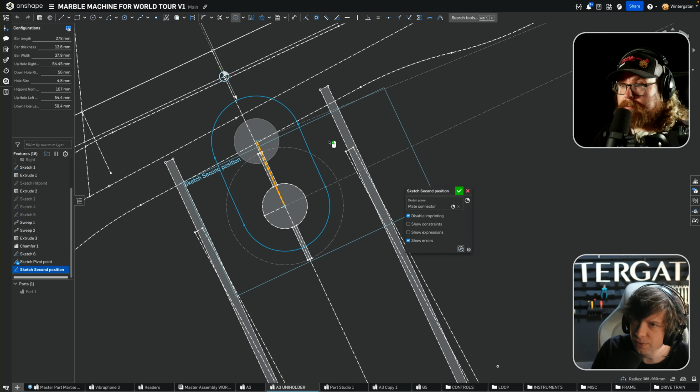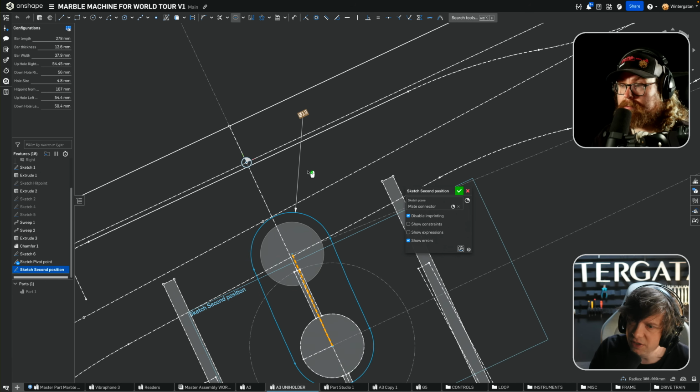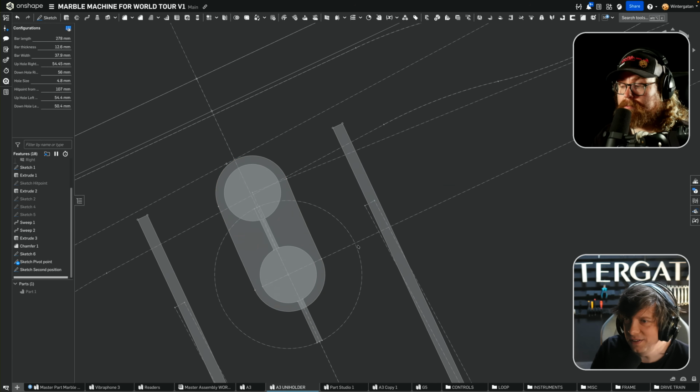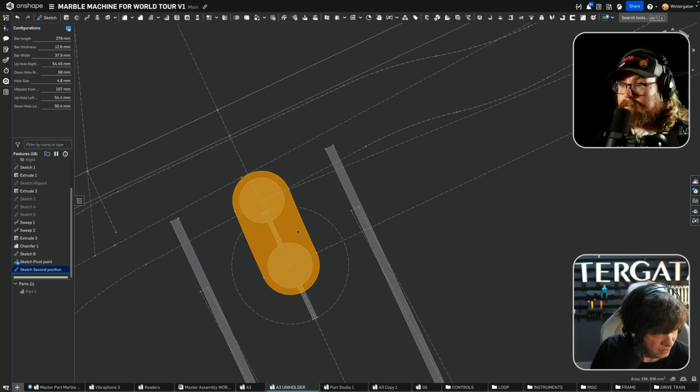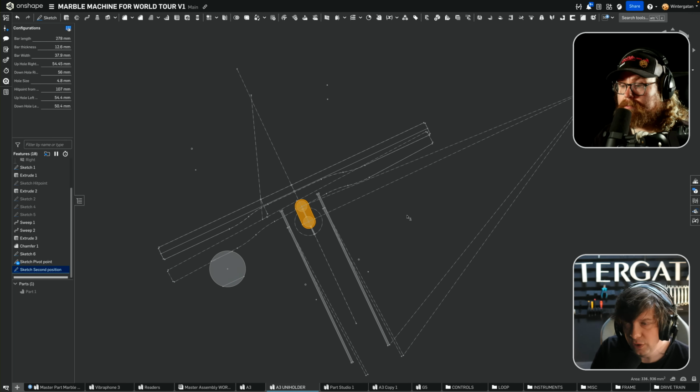So now we just want to decide how much space we want around the shaft. So say the shaft is 10 millimeters. Do we want 3 millimeters of space, perhaps? We got our slot. That should be the correct slot for this pivot point location.